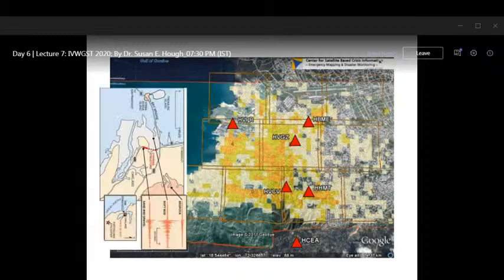This seemed similar to the 1989 case that you had. I turned it on its side. So this is Oakland, this is Haiti. But in both cases, you have hard rock, and then you have older sediments, and then you have softer sediments. So the expectation was that the strongest shaking was going to be where you have the softest sediments. But in fact, in Port-au-Prince, there's a foothill area. There's a Plio-Miocene fan complex that has a lot of small-scale topography. So this isn't just a mountain and a flat valley. It's really mountains, foothills, and valley.